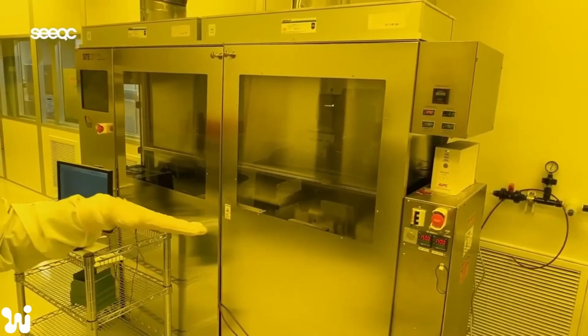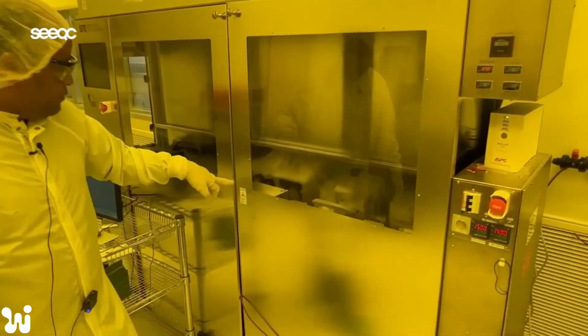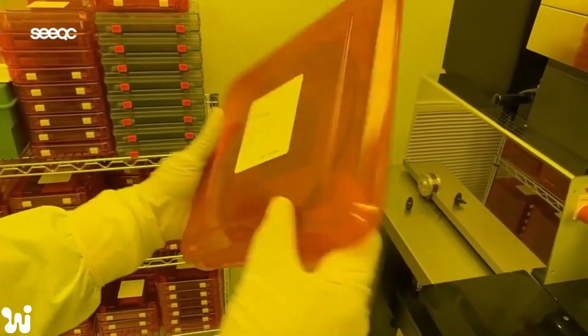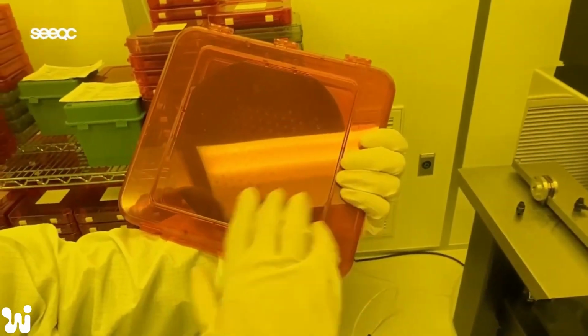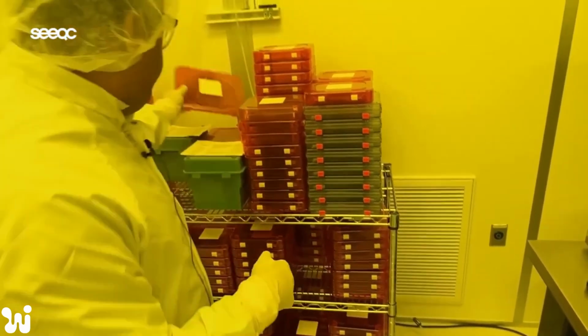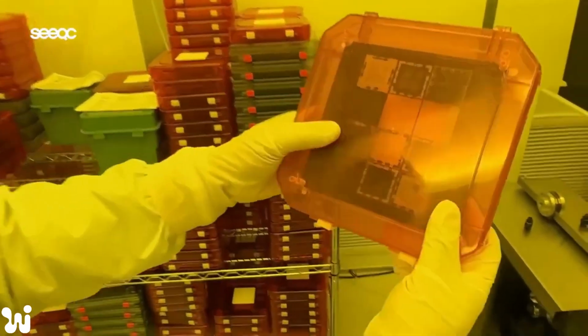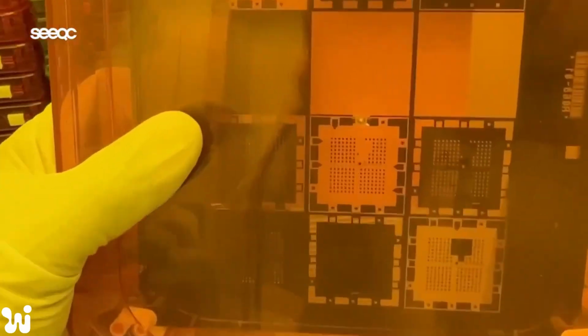This machine is the one where we first put the resist on in one of these chambers here, and then there are some baking chambers here. So once it puts the resist on, this one is 1-to-1. Basically, whatever you see here will be directly printed onto a wafer. And then we have this one, which is reduced 5 times in size and exposed onto the wafer. So using that machine that you see over there.